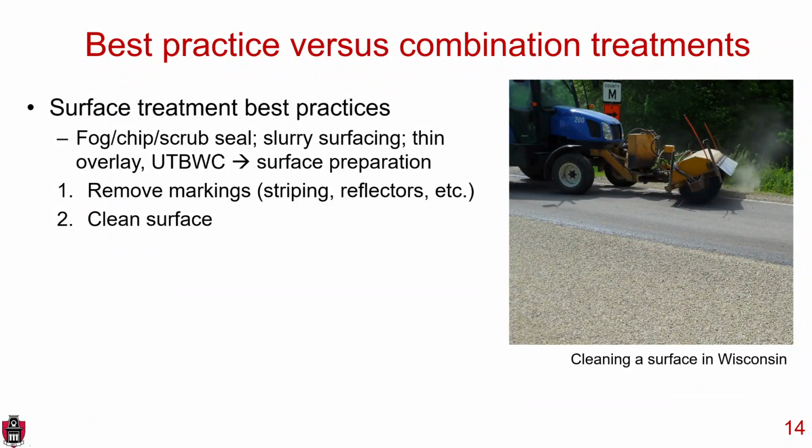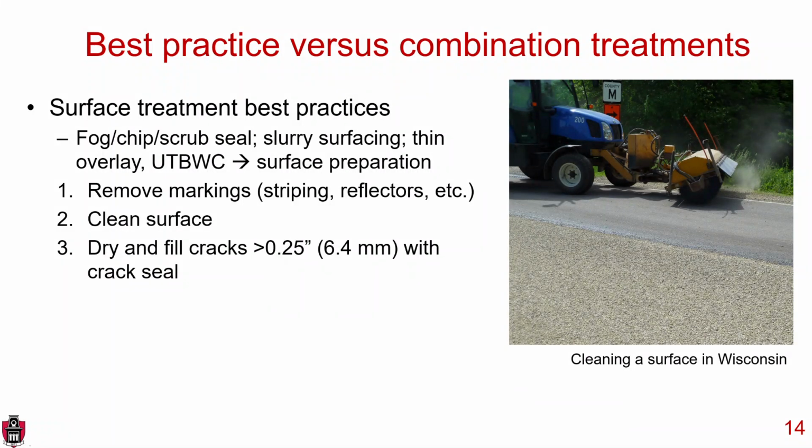You want to clean the surface. You want to dry and fill any cracks greater than 1/4 of an inch with crack seal. This is all proper surface preparation before you place, for example, a chip seal, which you can see on the right. If you do not do this, your surface treatment will not perform as designed. So in my mind, these are best practices.